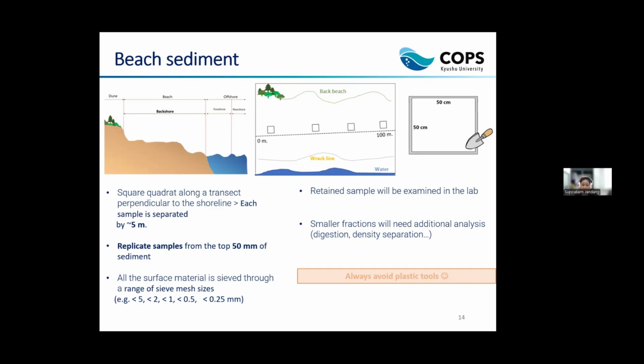Then you use a metal scoop like this, collecting the sand or the sediment from the top and digging down a little bit, to a depth of approximately 5 centimeters from the surface to the bottom of the sediment layer, only 5 centimeters.